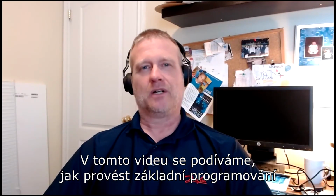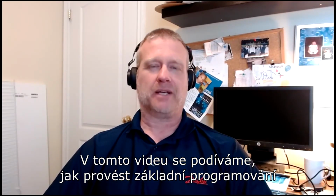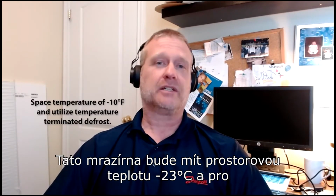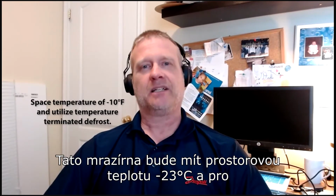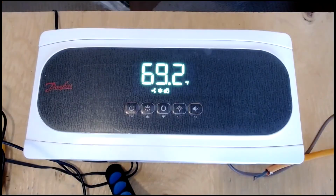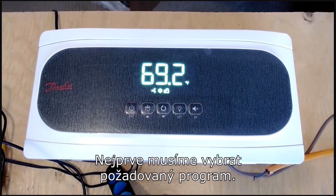In this video, we're going to look at how to do the basic programming of the Optyma controller for a walk-in freezer. Now, this freezer is going to have a space temperature of -10 and utilize temperature terminated defrost. To do the initial programming, we first need to select the desired program.